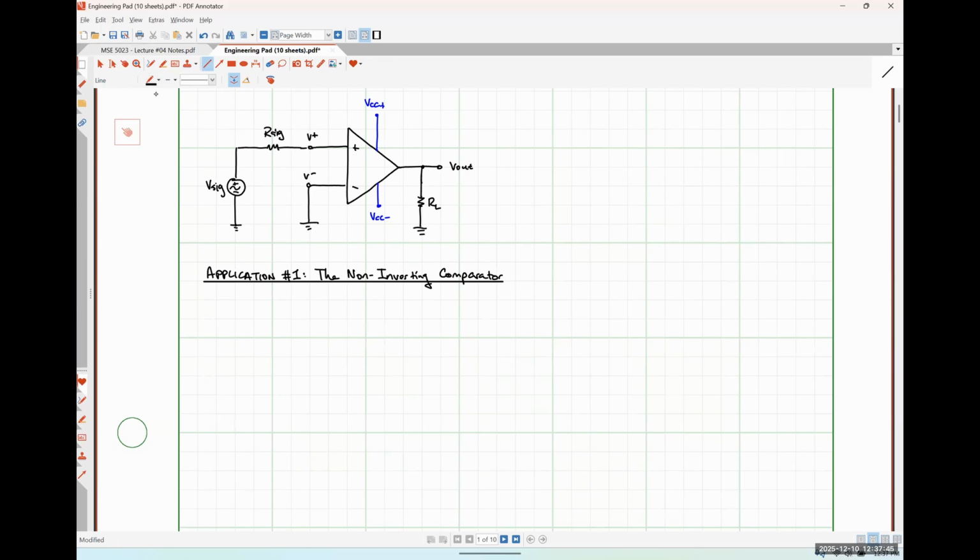So particularly it's looking at the voltage of the input signal, and it is going to compare it to some reference signal. And then it is going to generate a specific output depending on what the result of that comparison is. Okay. So we could use something like this to say turn on a warning light if an output voltage gets too high, or if our signal generator was like a thermal sensor that generates a voltage depending on the temperature. This could be an indicator light that says, hey, don't touch the stove right now. It's still hot, which is literally what's part of your stove.